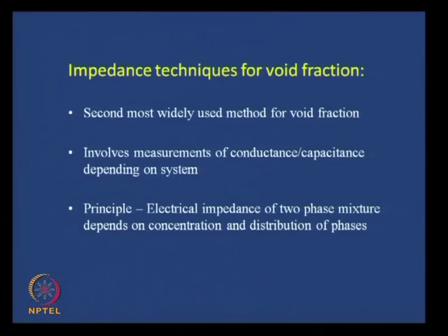So, for more accurate measurements, very often we would prefer to exploit the difference in dielectric constant as compared to the difference in electrical conductivity. Now, when we are using it, what do we have to do? We have to measure the conductivity when the tube is full of water, the conductivity when the tube is full of air, if it is an air water mixture, and then the conductivity when the two phase mixture is flowing.